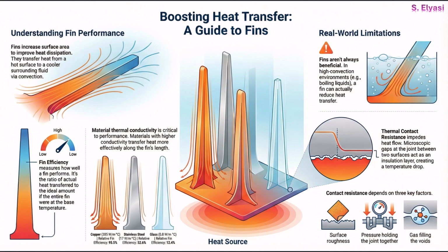Now, to measure this, we use something called fin efficiency. Think of it like this. It's the ratio of how much heat the fin actually transfers compared to the perfect ideal amount it could transfer if the entire fin stayed as hot as its base.